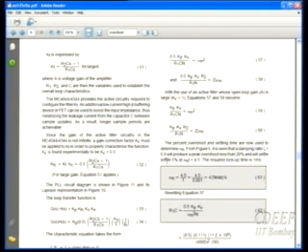Zeta equal to 0.8 will produce a peak overshoot less than 20% and will settle within 5% at omega n t equal to 4.5. Therefore, lockup time is 1 millisecond, and we want to have 1 millisecond lockup time. Therefore T will be 1 millisecond, and omega n will be derived here.